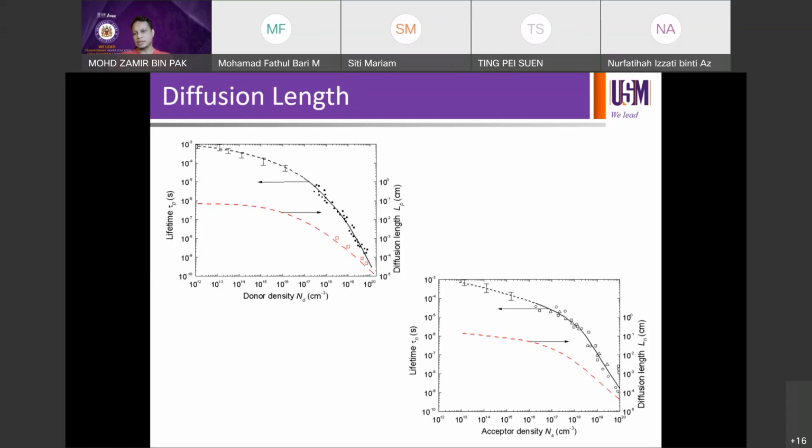For example, you're going to learn later on that if you talk about a solar cell as a PN junction, the P layer is typically 10 to the 16, and the N is a very thin layer, on the order of 200 nanometers, while the P is close to 200 microns, and the N has to be heavily doped.